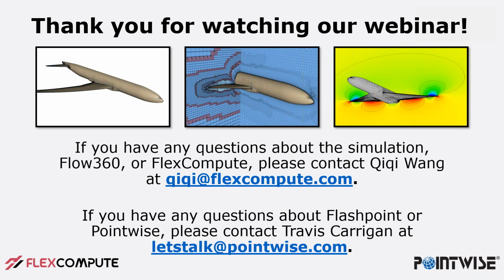Good question. How do you apply Flashpoint in an MRF scenario, like a propeller? This is a good question because it's something that we've recently done. Flashpoint simply requires you to select a model, and you can actually select multiple models before entering the automatic surface mesher. It will automatically generate a surface mesh for each model that you have selected.